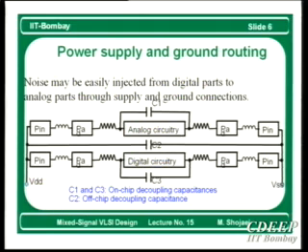Yes. Externally they are shorted, but internally they are not the same. See, consider you have an IC which has two VDD pins. Then you connect them on a PCB track. From outside they are shorted, but from inside they are not. Therefore, if there is a switching current coming from this module, that will come only from here. See, because the outside track doesn't have a very high impedance, right?